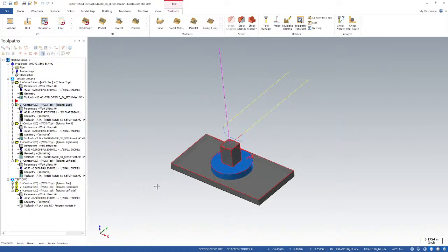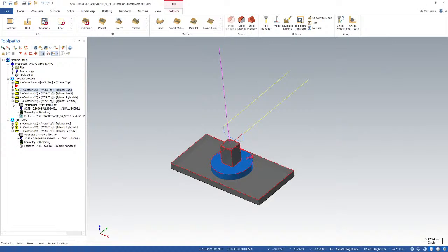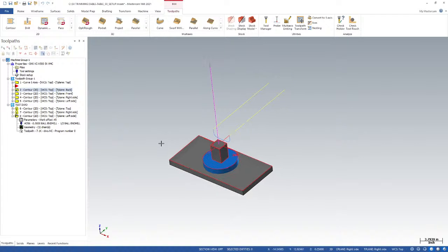The easiest thing to talk about is curve 5-axis. So one of the things I've done here, this is an older, really simple part file that I use for setting up a table machine. So one of the first things we should talk about when it comes to 5-axis, we've really got to take into consideration the type of machine that we're setting up and we're cutting on.